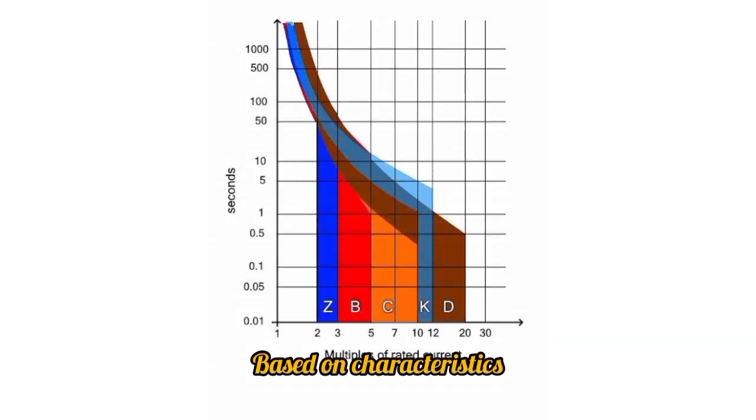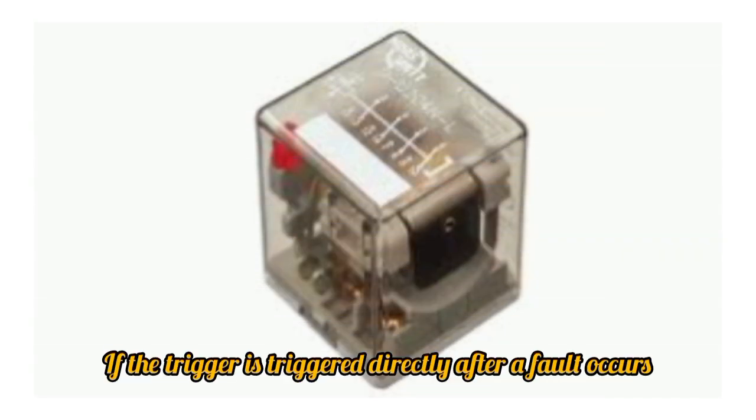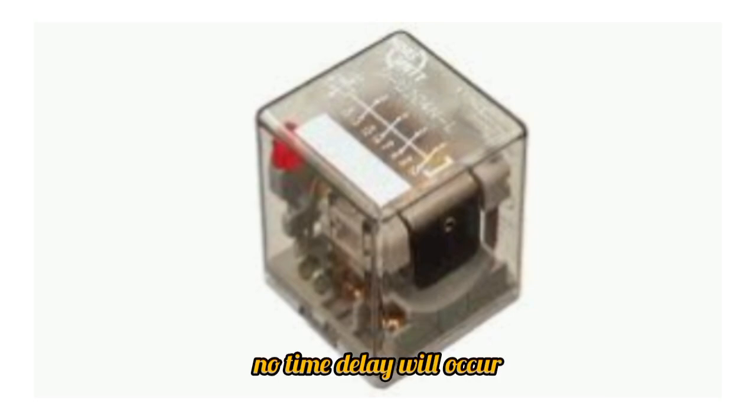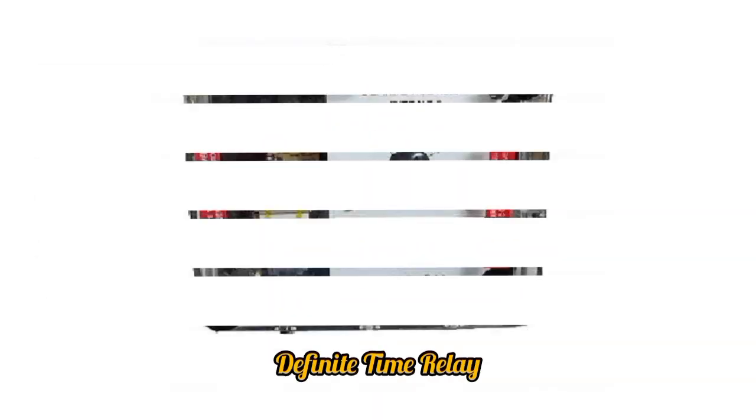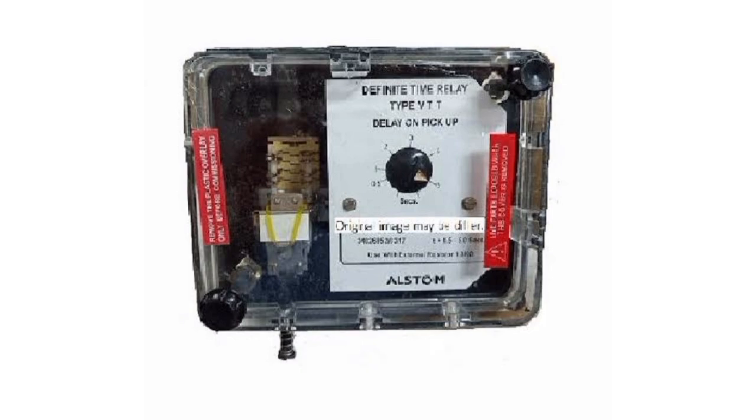Based on characteristics. These classifications are based on their tripping property. Instantaneous relay. The trip is triggered directly after a fault occurs; no time delay is involved. Definite time relay. Only activated if the fault stays in place after a certain time.